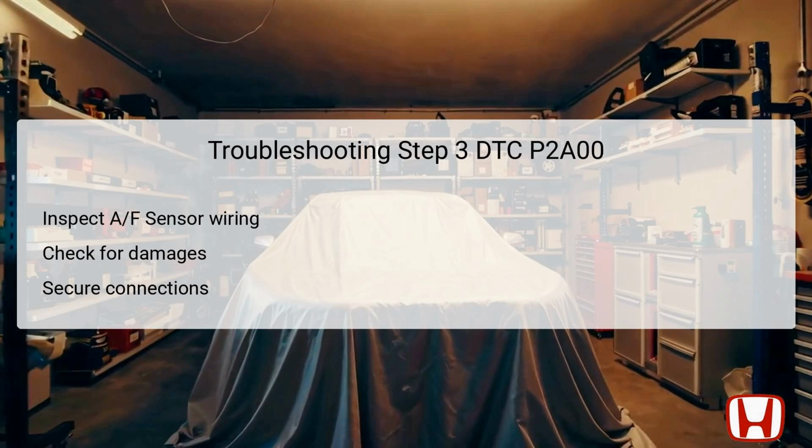Once DTC P2A00 has been reviewed post-test drive, the next troubleshooting step emphasizes inspecting the AF sensor's wiring and connections. First, visually examine the wiring harness leading to the AF sensor for any visible damages, such as frayed wires, corrosion, or disconnections. It's crucial to ensure that the wiring is intact, as any faults here can lead to incorrect signal transmission to the PCM.